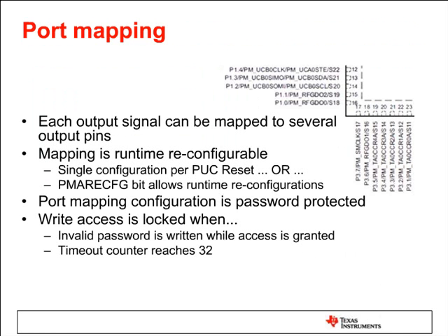Port mapping. I like port mapping because it makes my life as a PCB designer a whole lot easier. I can take any of these, and I just took a little sample here of the lower left corner of the device, but I can take any of these PM underscore signals.